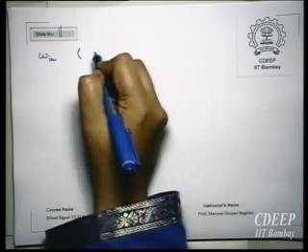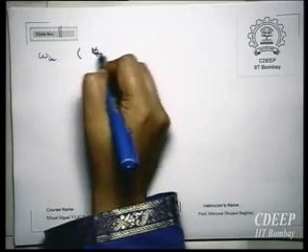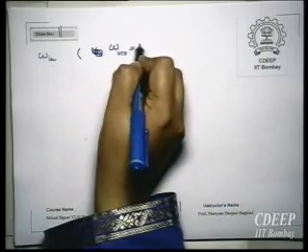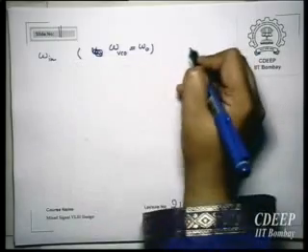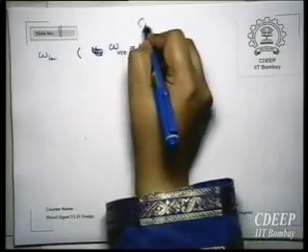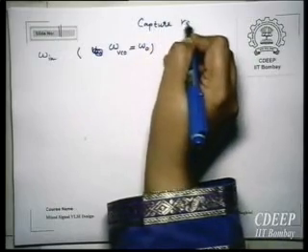When loop is not locked, I have a phase frequency detector. Essentially, all phase frequency detectors are some sort of multipliers. So you assume you have a multiplier now, right? And you have an input frequency. We have a square wave, but to make analysis simple, just assume first harmonic of that square wave. Okay? Therefore, I have some omega in, and loop is not locked. So omega VCO will be omega 0. So, this is for capture range. Therefore, loop is not locked.